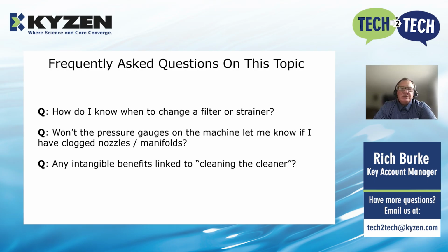In some cases, you might have a pressure gauge pre and post filter, for example, let's say a bag or cartridge filter, and there might be a pressure gauge on the upstream and downstream side of that filter. So as that filter were to become clogged, you would be able to detect or see a change in pressure from the pre and post filter, and that can be indicative of when a change is required.